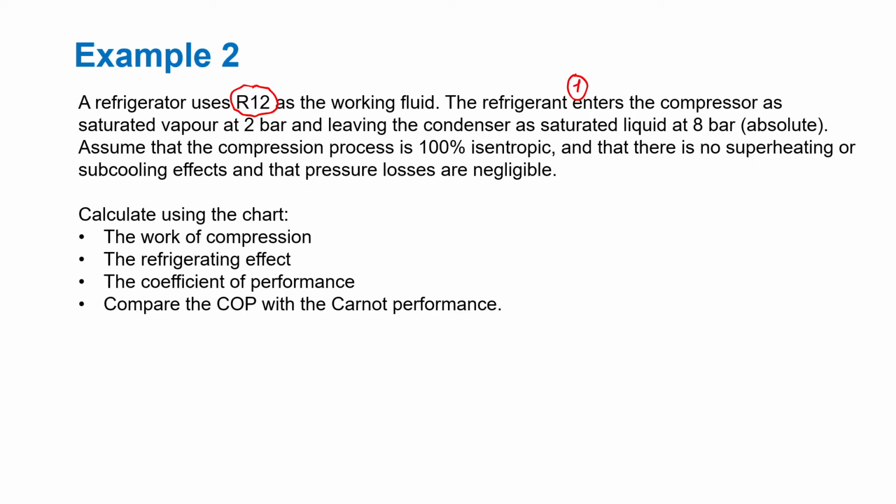Leaving the condenser is point 3, as saturated liquid at 8 bar. Assume the compression process is 100% isentropic, and there is no superheating and no subcooling.